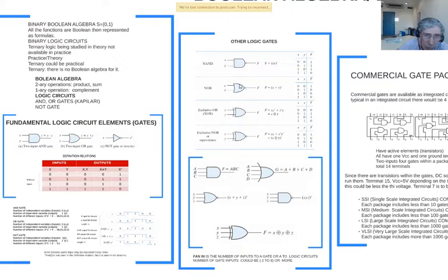These four of them, once again, have got 2 inputs, and the definition relations are given here. For the NAND gate, you can consider that there is an AND gate, and its output is connected to the input of a NOT gate like that, and then you get the output. So what you get is AND, which is x times y. It is a product term. The prime of it, the complement of it, is going to be this one, isn't it?